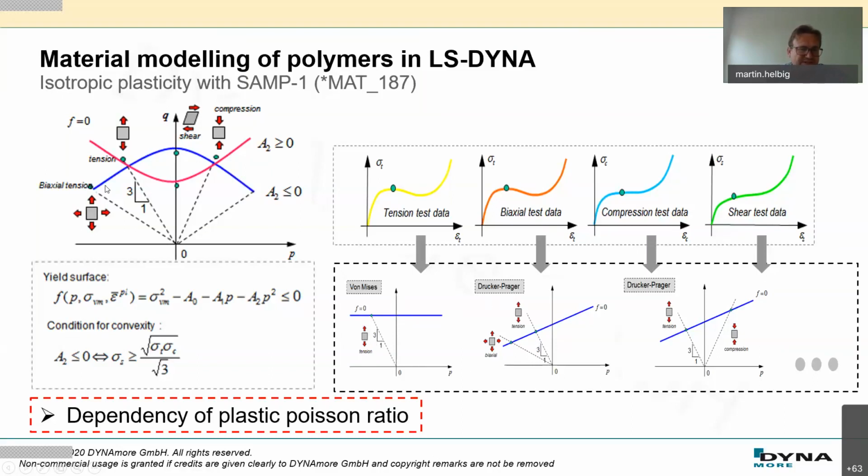This is shown in here. So some curves for biaxial tension test, tensile tests, some shear tests, and some compression tests. And the yield surface will automatically be created, as we see here. There's also a flag for the case that we don't want a yield surface like this. It then switches, or it moves the shear point to this. And the idea of the material is to describe the yield behavior of a polymer as well as possible.